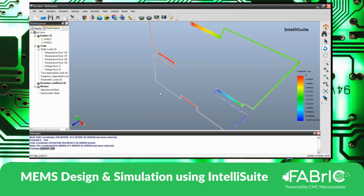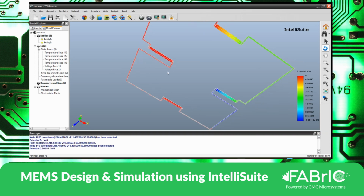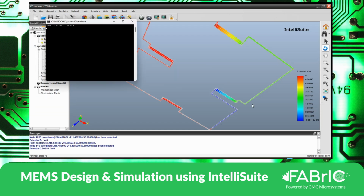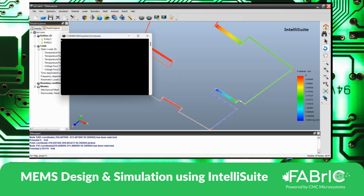Now what I can do is, for the applied pressure, change the pressure value and redo the simulation again. If we do that, then we can check the sensitivity of the device. So we can parameterize the pressure value over a range. I can show you that in another window. I can close this. So it means we can apply pressure in steps also.